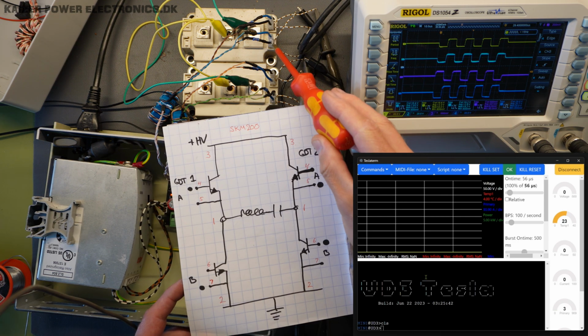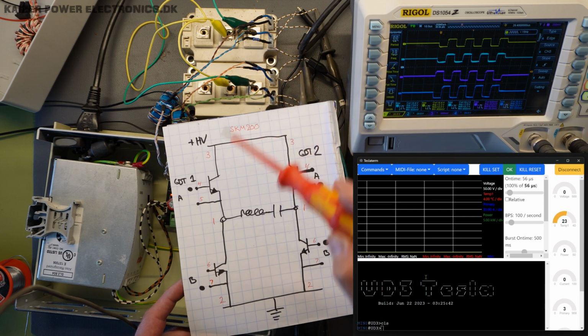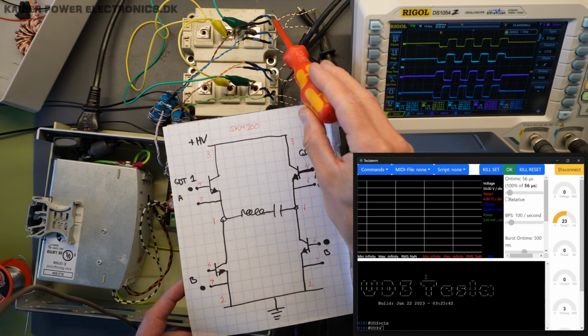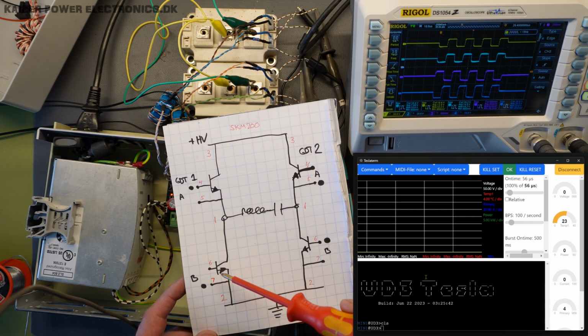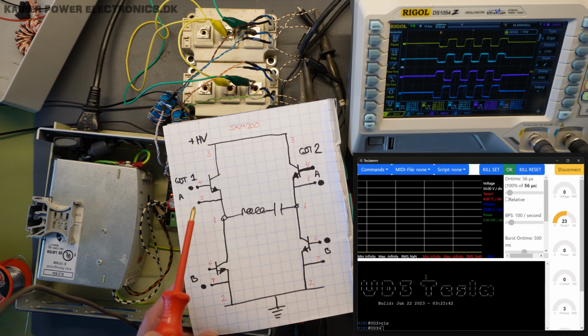The second row here, that is the first IGBT, or the upper one, and the upper one here is the lower one. And it's connected to the oscilloscope through two differential probes in order to not short out the ground. As we can see, we measure on the gate and the emitter. And that becomes a problem if you connect your ground clip here, and you also have a ground clip down here. So that's why you need two differential probes to measure the two upper IGBTs.